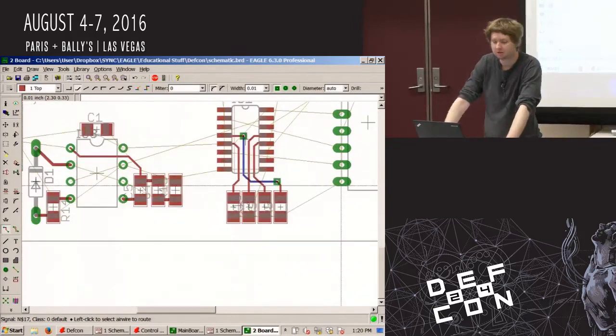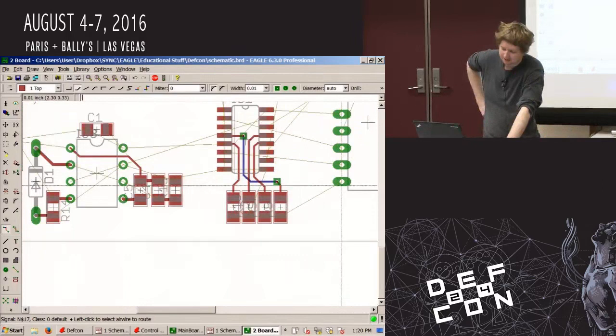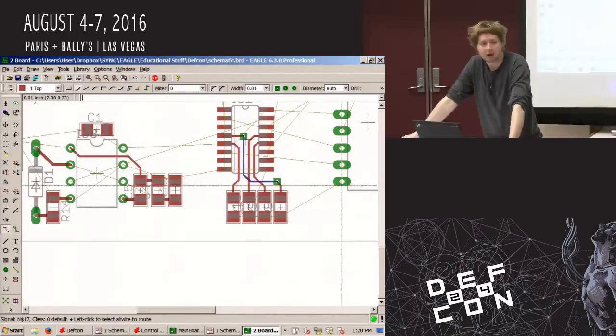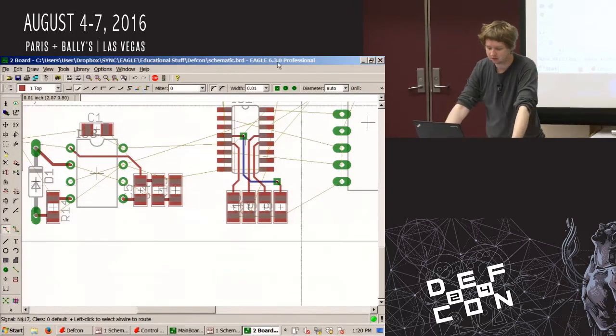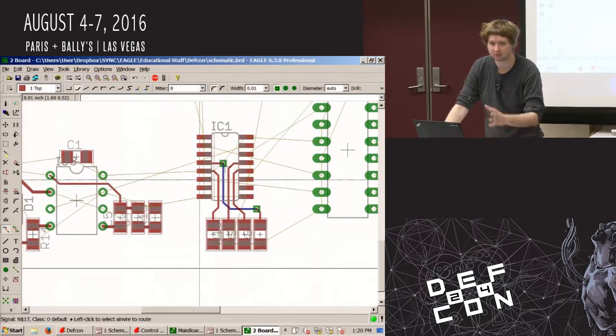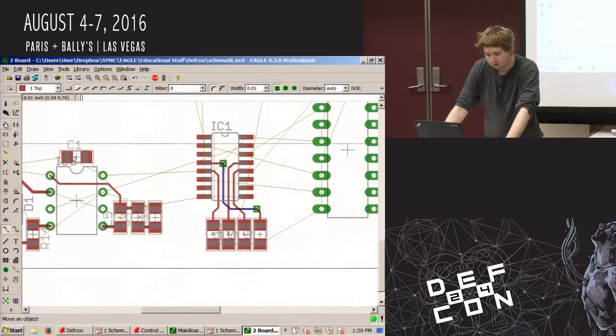So just be cognizant of that. But if you have a small via and you fill it in with solder, it can actually take a lot of power. So you can use that as an efficient way of running power between layers. It'll take way more power than a trace, unless it's just a massive trace.